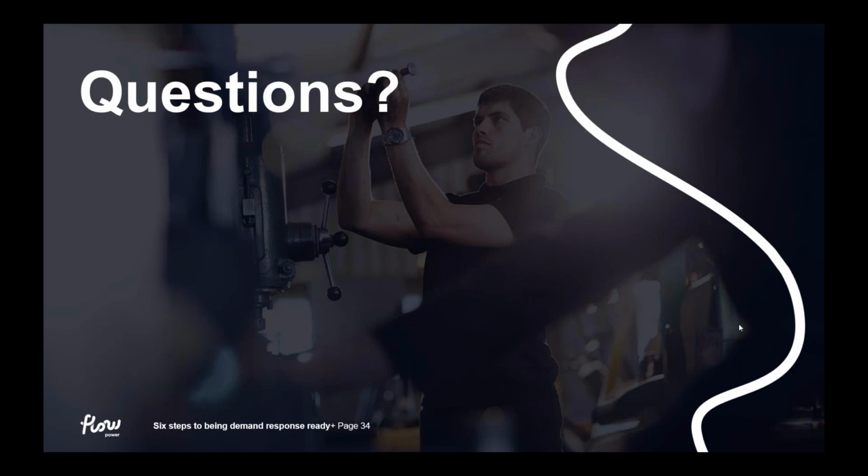All right, so we've got a question that's come through. What sort of equipment infrastructure did the agribusiness have to install in order to manage events? So this specific customer has been with Flow Power for quite some time. They manage the event in 2 different ways. Initially, they just send out staff manually to switch off the pumps. It's as simple as the staff leave from the central hub, drive out to the farm where the pumps are located, and initiate a shutdown sequence, which is a controlled shutdown of the pumps, and then wait until the event has ended. That was how they managed the event for some time.